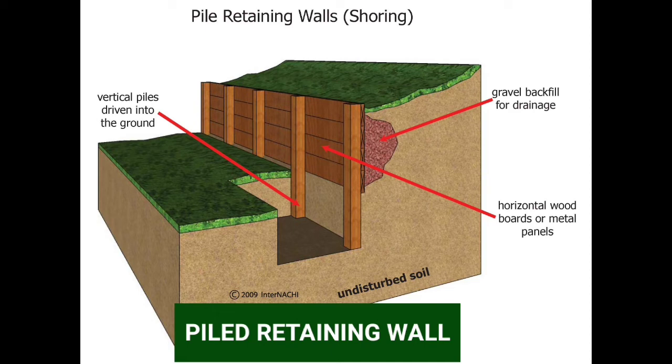Second point, it is employed in both temporary and permanent works. Third point, piled walls offer high stiffness retaining elements which are able to hold lateral pressure in large excavation depths with almost no disturbance to surrounding structures or properties.